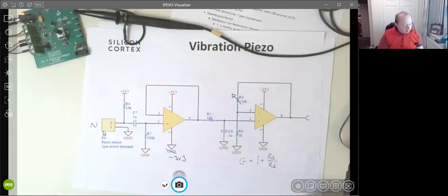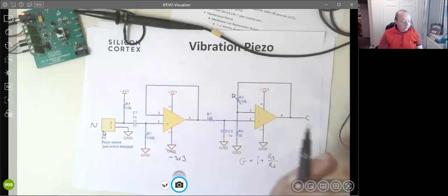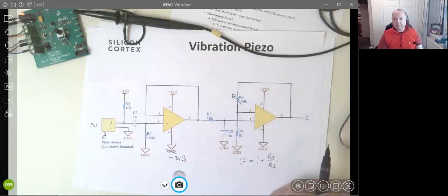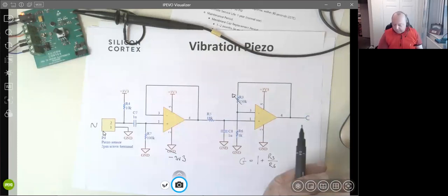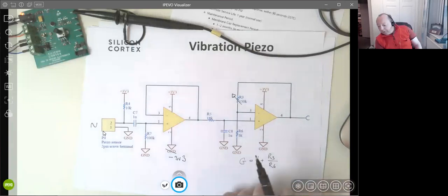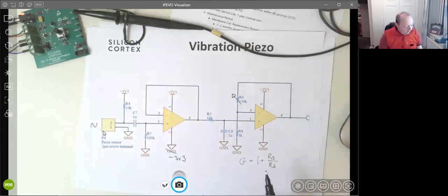That will probably depend on what sort of frequency you've got coming in. I mean, for audio, well, audio is going to be sub 40 kilohertz for sure. Accelerometers are usually good up to, well, most of them, certainly the MEMS devices, are good up to about 1 megahertz. If you want to go above 1 megahertz, they start to get quite expensive.